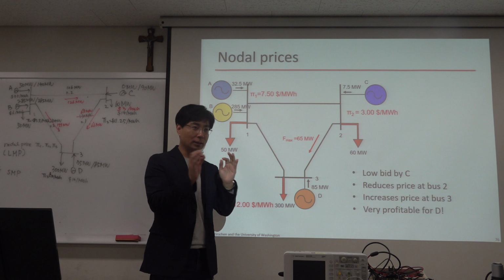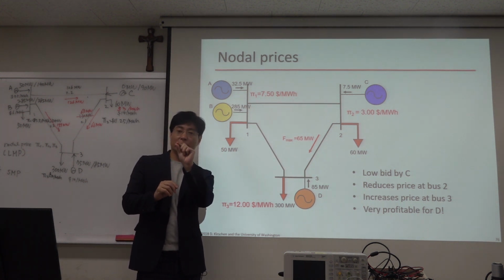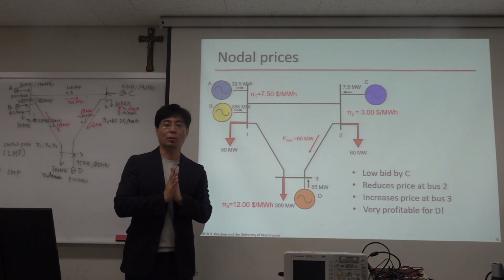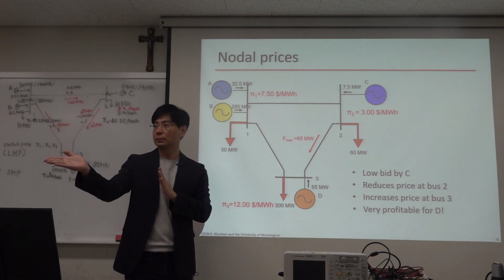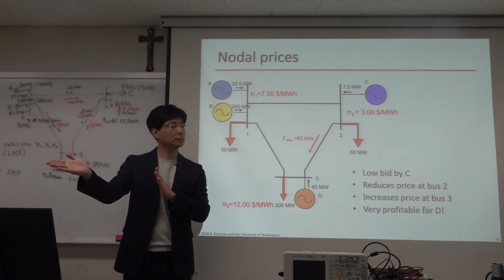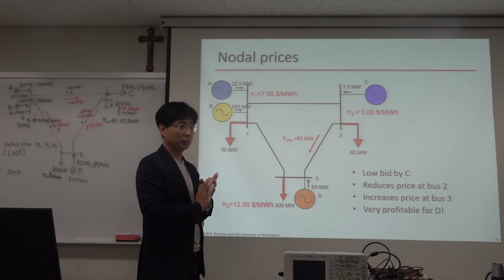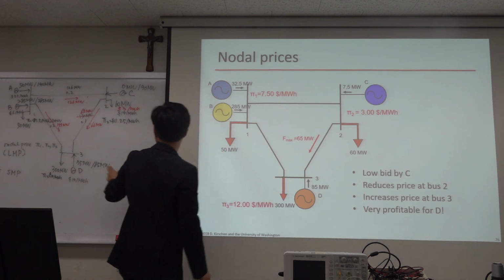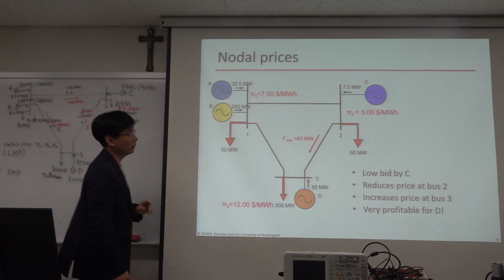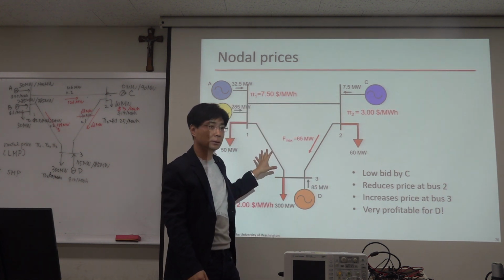So you obtain, by the way, when you obtain delta P1, what you need to do? One thing is missing. What is missing from my statement? Reactance is already, you should already consider that when delta P1 is injected, it is split like that, considering the reactance. When delta P2 is injected here, it is split like this, considering the reactance.